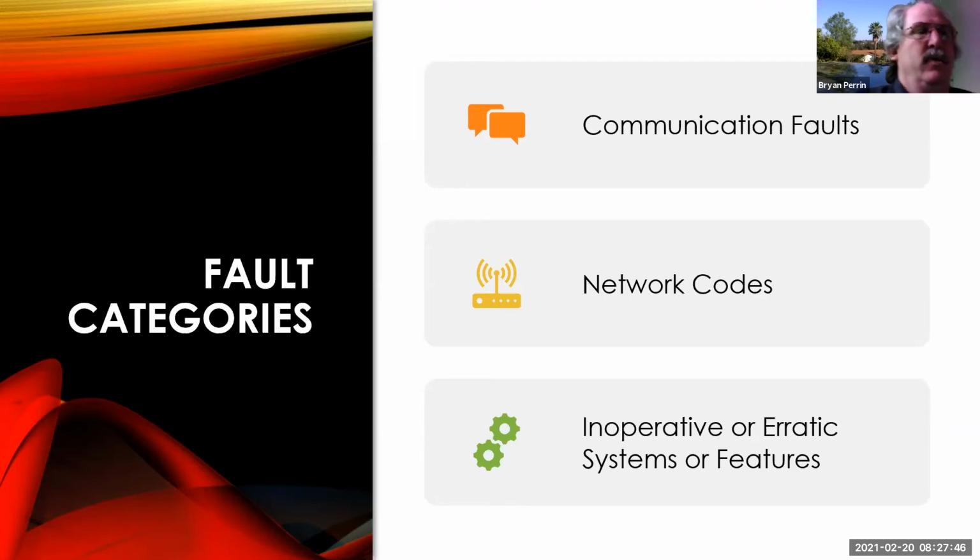What I can tell you is that probably 80%, if not 90%, of network communication issues, after you eliminate power at pin 16, are a bad DLC. The pins get spread, the wires on the back of them get broken, things like that. So probably 80% plus of the time you can't talk to a car, once you make sure you have power at 16 and ground at pins 4 and 5, it's a bad DLC.